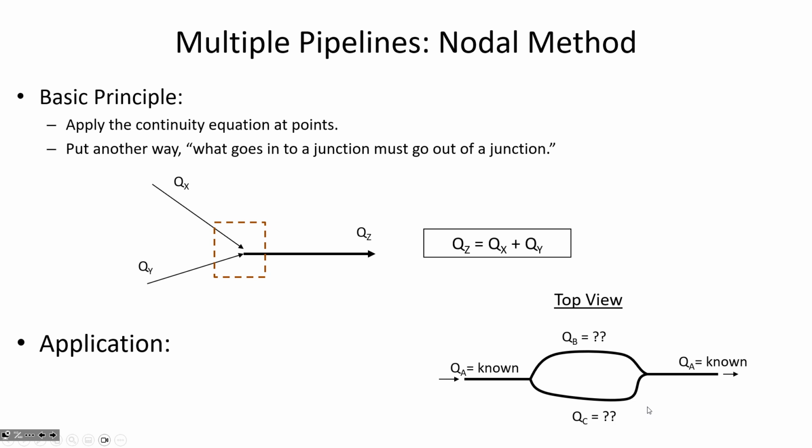You can have inorganic materials like iron, manganese precipitate out, and it could clog valves and fittings. It can be disinfection byproducts, which are organic materials. It could be the formation of biofilms. So it's just, as a matter of good practice, from the water quality standpoint, good to have, if you've got